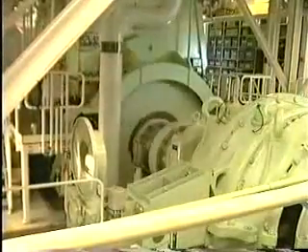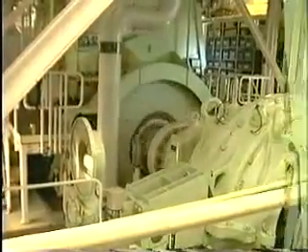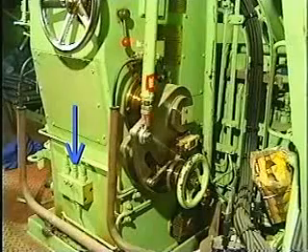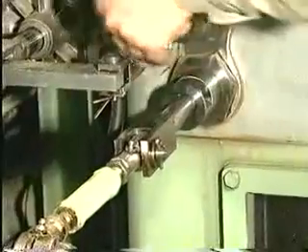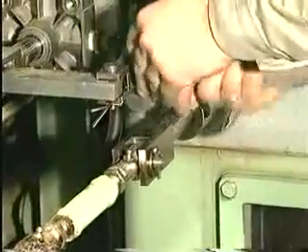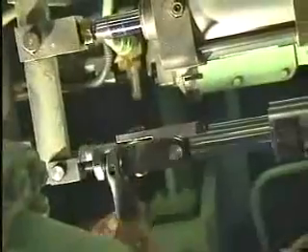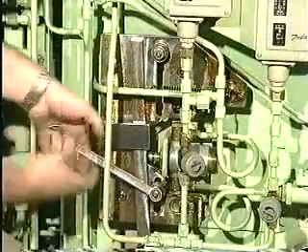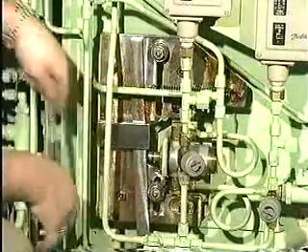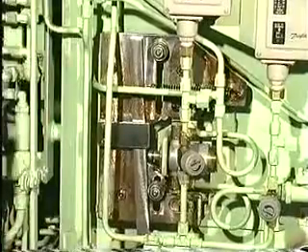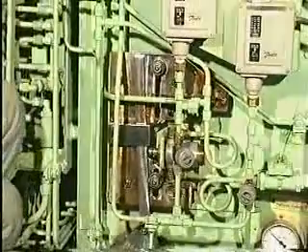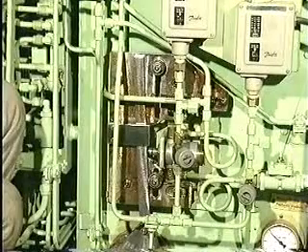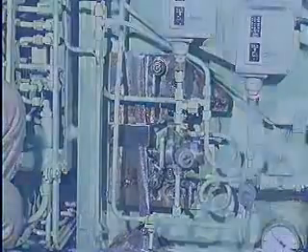Start the engine and run it up to a load corresponding to the breakpoint. Make sure that the control air pressure is able to pass the changeover valve. Fine adjust the links so that the maximum combustion pressures corrected to ISO ambient conditions are uniform and have the required value. Load the engine until it corresponds to 100% MCR and fine adjust the lowermost pivoting point so that the maximum combustion pressures corrected to ISO ambient conditions are uniform and have the required values.